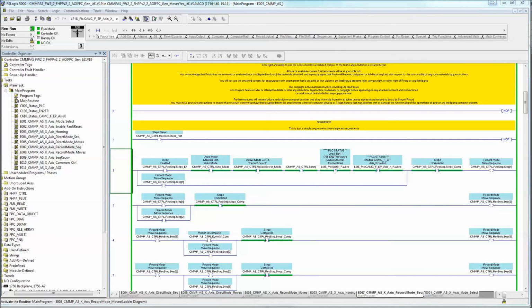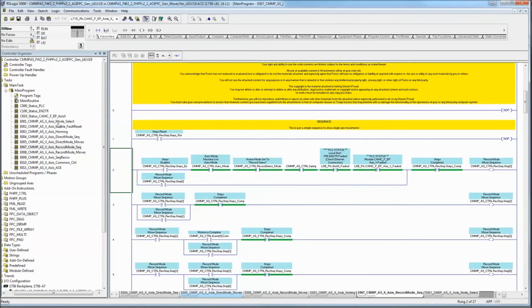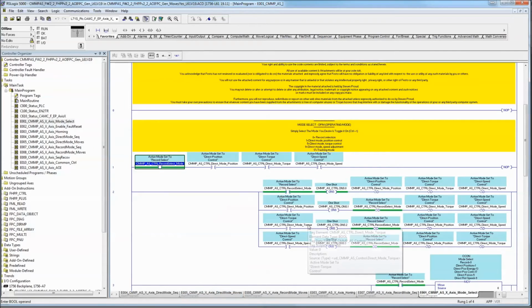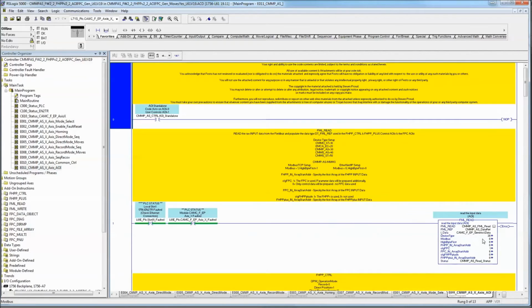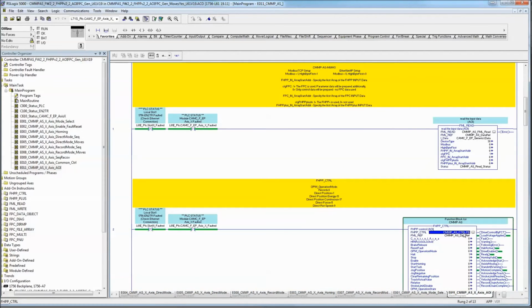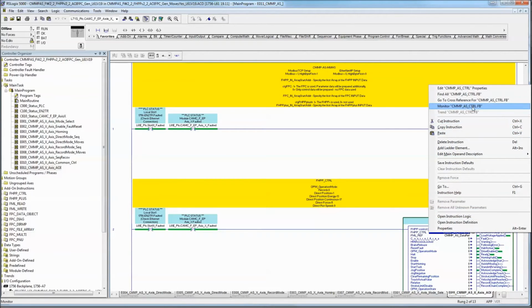Okay, so the last step here is adding some of your own code. I have gone through and added some code that acts on the function blocks. Whenever you go to a function block, the whole concept behind the function block is that there are tags already associated, and that's what maps to the real world.